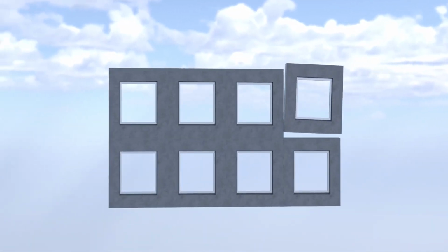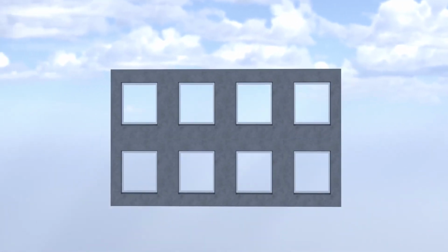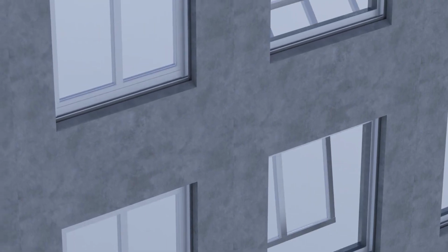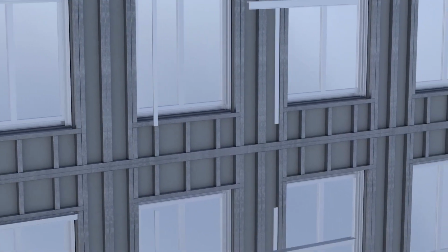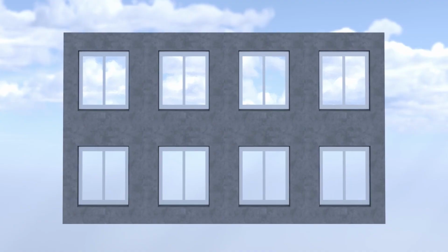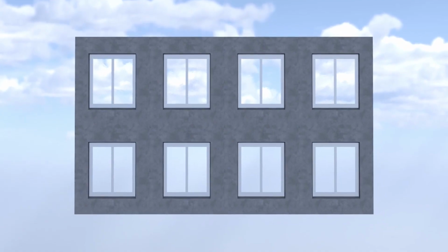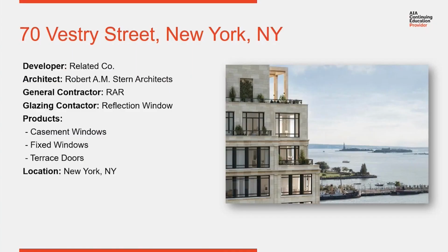The modular panels are stacked on the building one by one. Then our windows are brought in from the interior and set, standing on the inside, into the receptor, and then stops are snapped on the inside to hold the window in place, and now it's completely built and assembled. And that's how a project like this was put together.